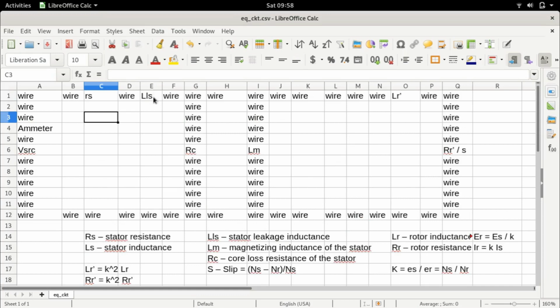So eventually we had said that we can simplify it such that we can bring both circuits, that is the rotor circuit and the stator circuit, to one pseudo frequency by dividing this slip term throughout the rotor circuit, right? And once we do that, we can merge these two circuits by creating them as equivalent parameters. So we have referred all the rotor parameters to the stator. As a result, we have this one single equivalent circuit which is connected together, which represents the entire motor.